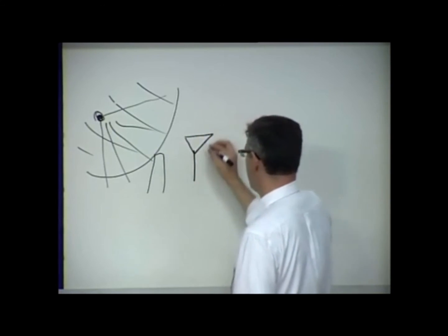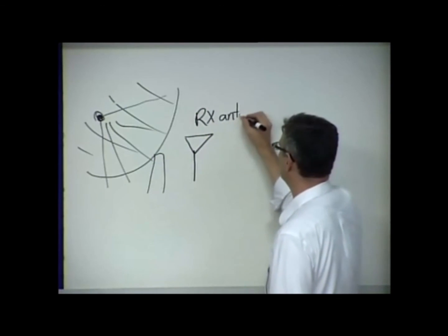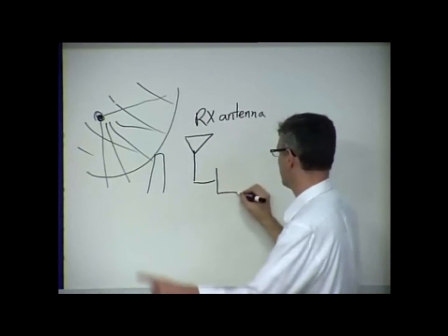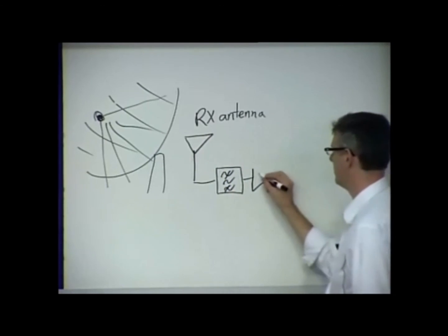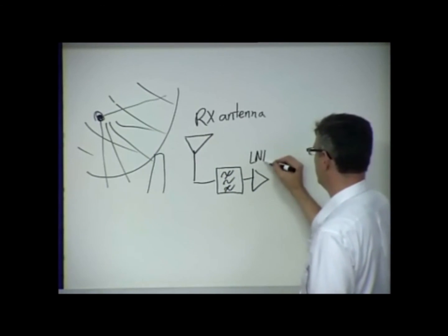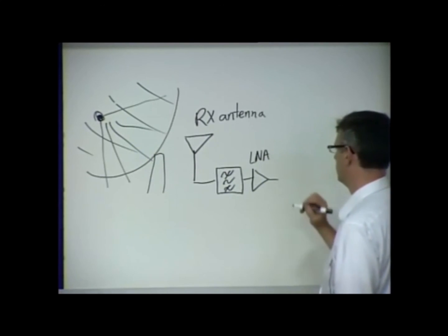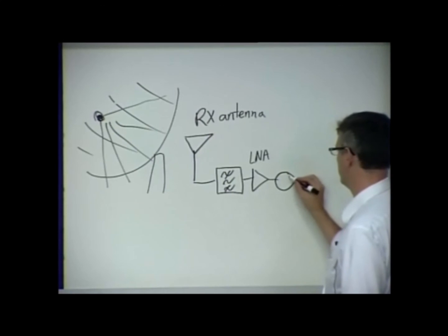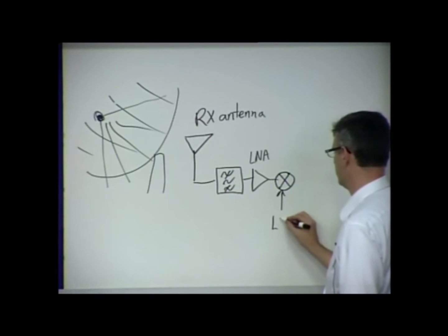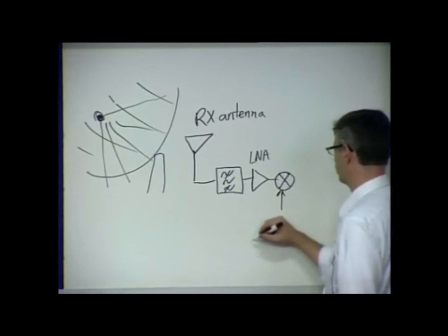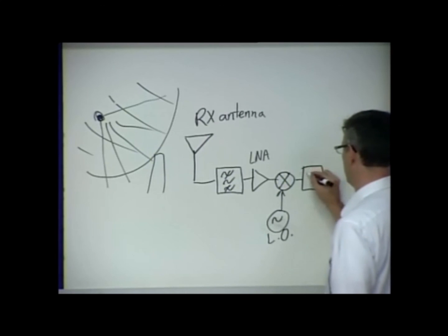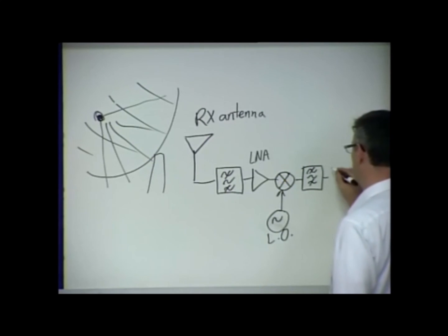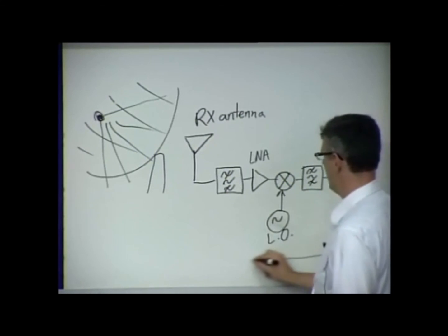So if I block diagram that, here's my RX antenna. We put a little bit of filtering, just like we did in the spacecraft. This is a universal RF principle, no matter where you are. Here's your LNA. And you have a local oscillator. Let me actually draw it: a circle with a squiggle in it. That's your local oscillator. Bandpass filter. Regular amplifier. And here's an example.